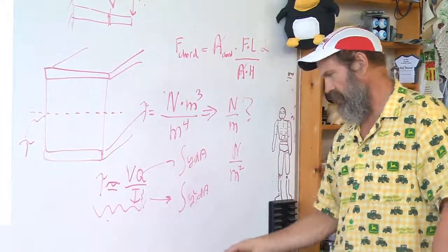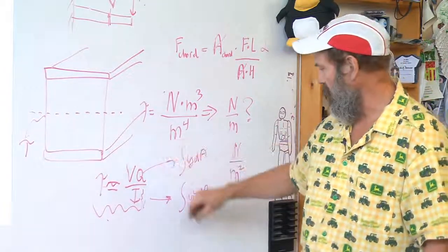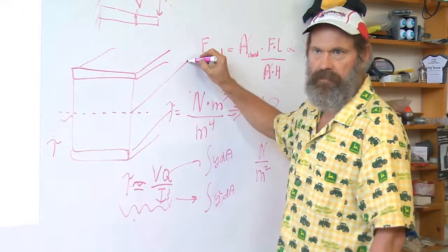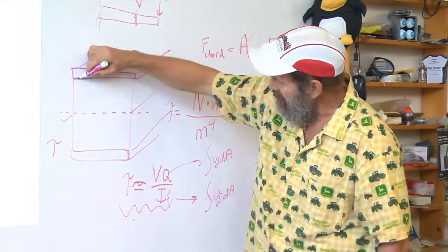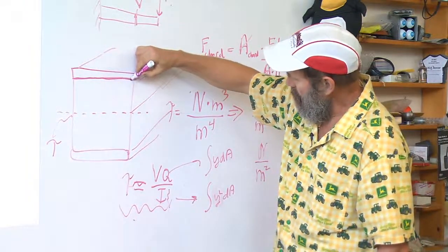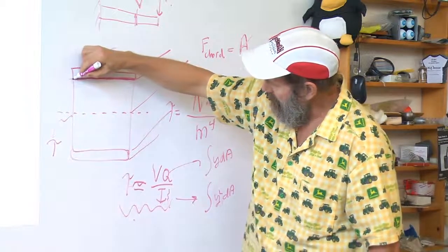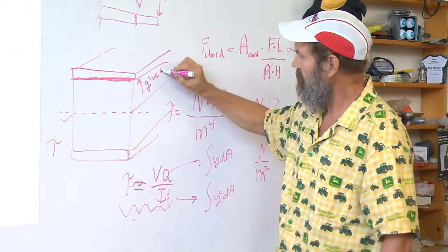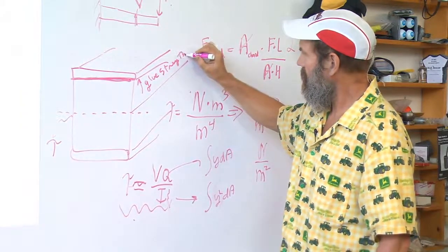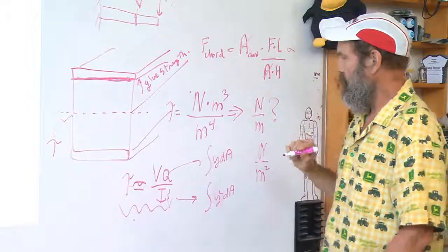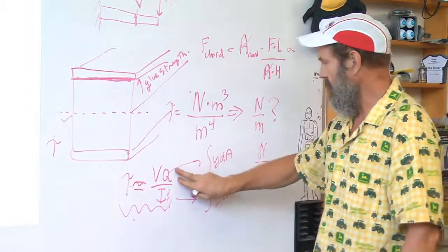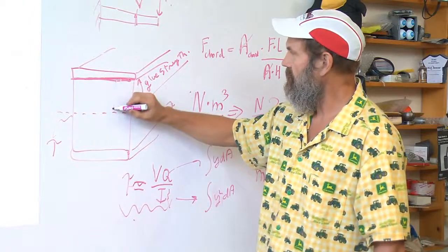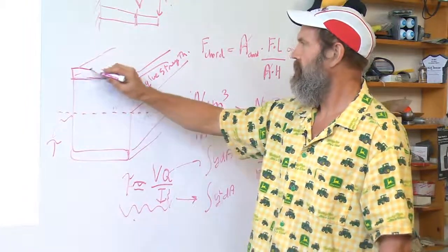The key thing is that you can calculate what is happening in this plane. You can also calculate the shear at this level to determine the glue strength. So this is starting to give you a hint of how to define Q. Is it the first moment of this area, or of this area?